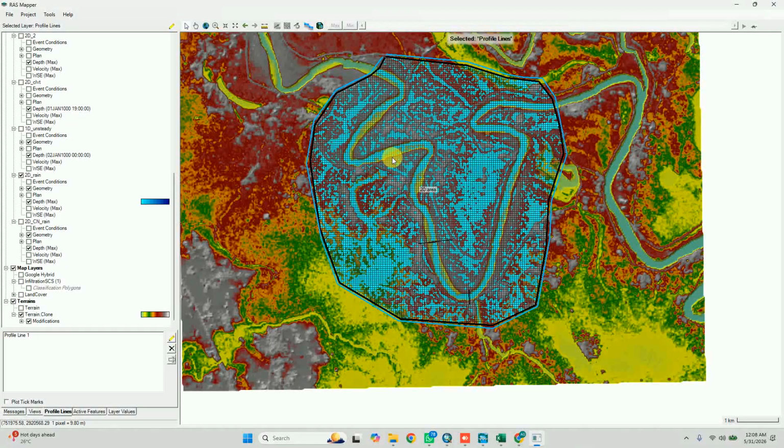and after that if water or flow is much more in comparison to the capacity of the channel, then water will spill out from the river and inundation starts from the river. This type of inundation is called river inundation or riverine flood, you can say. But if you want to know, if rainfall is taking place in this area, which area will inundate and what inundation will take place by the rainfall.